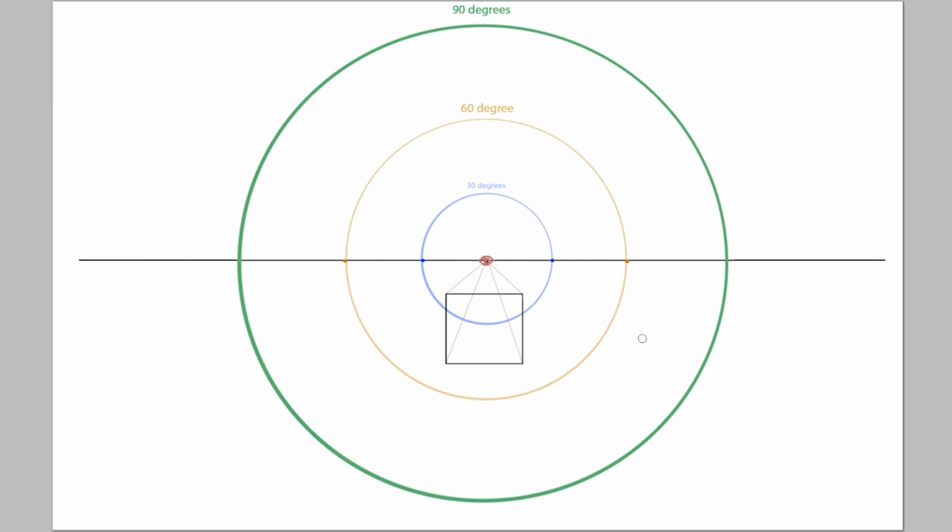But now we run into a problem. How do we know how far back to go? At the moment we know this distance is going to be shorter than our initial line, as it's foreshortening back to the central vanishing point, but we don't know exactly how long it's going to be. Lucky for us, there's a way to work that out.